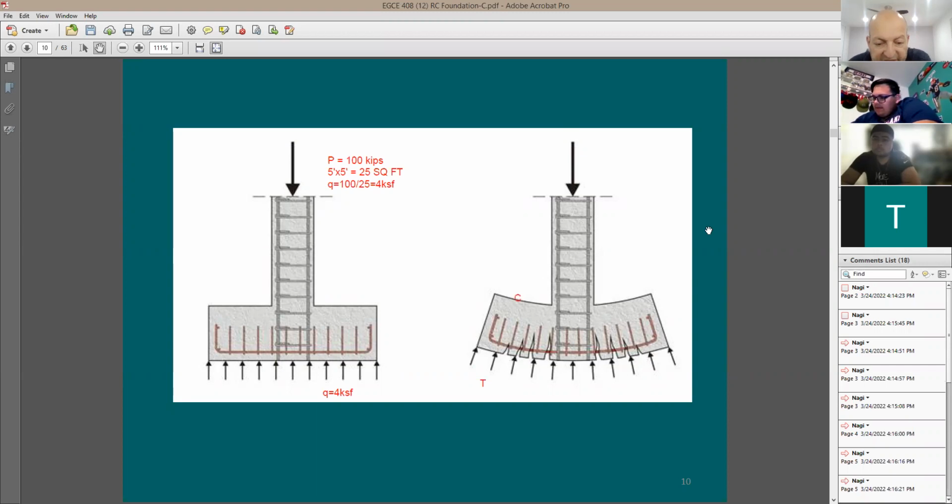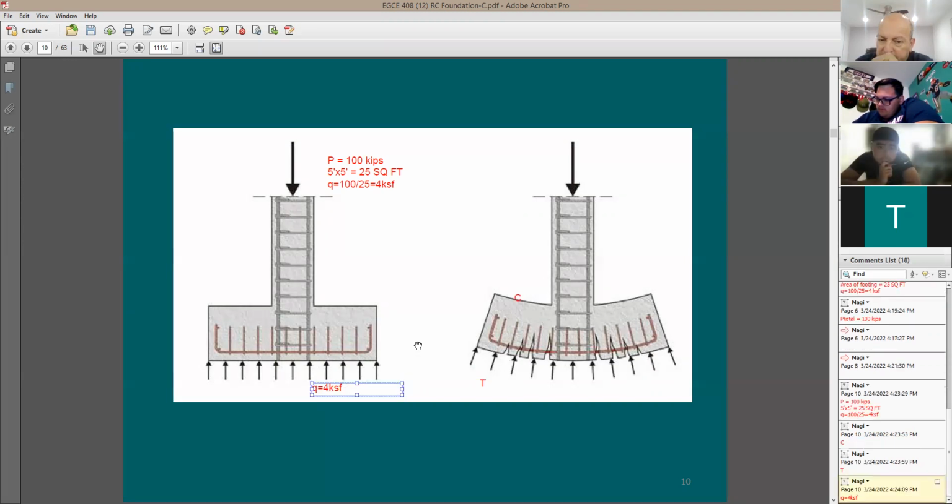So actually when I do footing design, I have two issues. Number one, be sure that you're not going beyond the allowable soil pressure. And number two, I need to design this reinforcing like any concrete member. So first, you size the footing so that this pressure is going to be lower than the allowed. This is going to be kind of soil design. This is not concrete design, right? This is not what we're learning in this course. We're learning how to do concrete design, right? For concrete members.